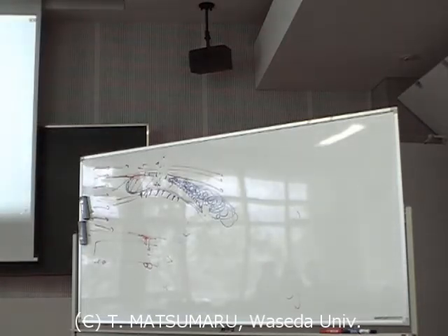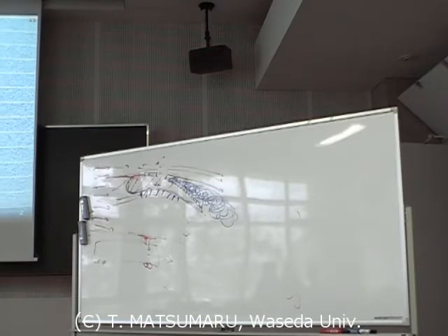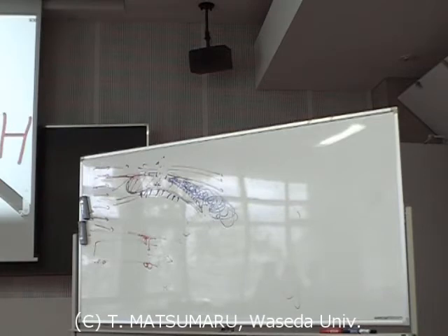As air flows around a curved surface, it would like to follow that surface all the way around. If air did not have any friction, it would flow around this ball symmetrically. High pressure at the front and back, low pressure at the top and bottom. And there would be no drag because the pressures are symmetrical and there is no friction. However, what you actually get in real life is a wake. This right here is particularly interesting because the air is going from an area of low pressure to an area of greater pressure. And that's kind of weird because things always want to go from a higher pressure to a lower pressure. But the air has enough speed and momentum to push through it.